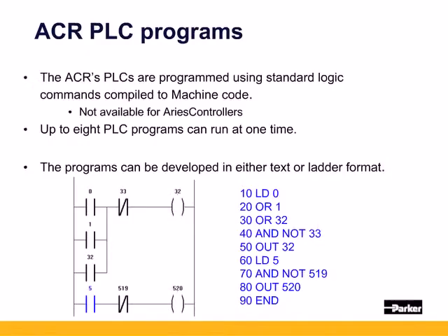Let's get started. ACR's AcroPLC programs are programmed using standard ladder logic commands compiled to machine code on download. These programs are available in all ACR controllers except the Aries controller. Up to 8 PLC programs can be run at one time. Programming can be done in ladder logic or text.